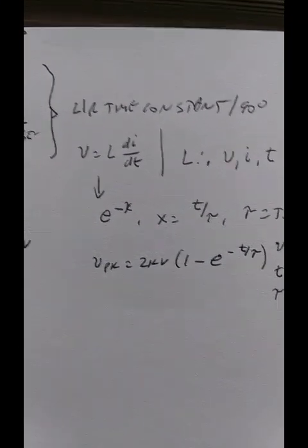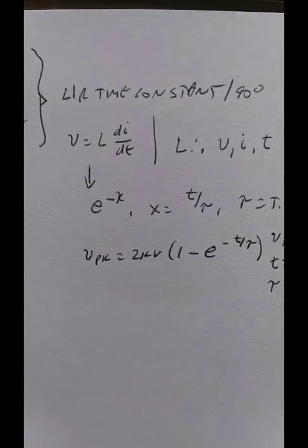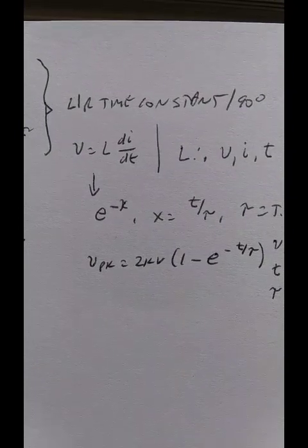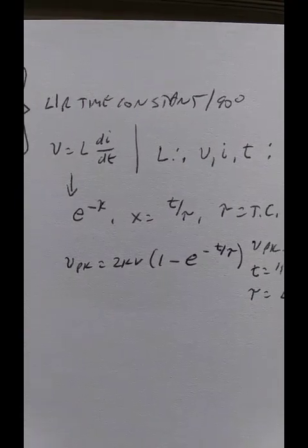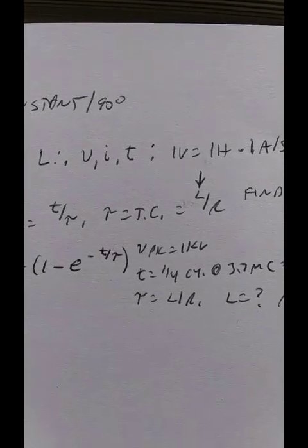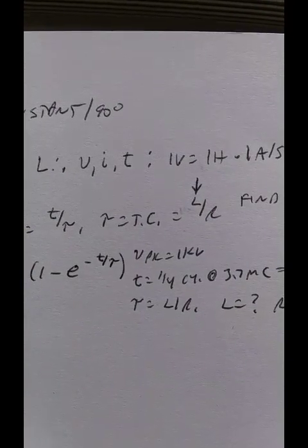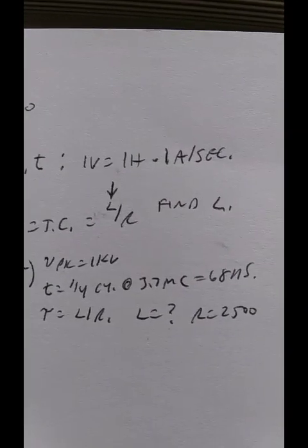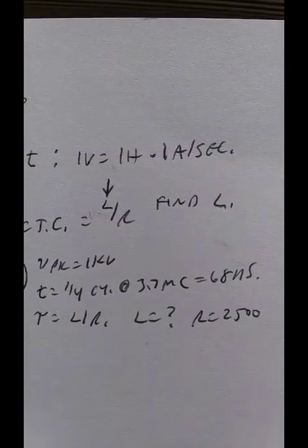The basic equation that describes an inductor is V_AC equals L times the differential of current over the differential of time. That's a differential equation. That dI/dt doesn't seem to make a lot of sense until we consider the basic definition of inductance. Inductance is proportional to AC voltage, AC current, and time. Well, what isn't? That doesn't help a lot. Everything depends on that.